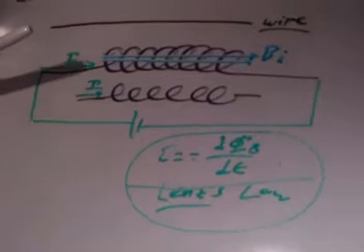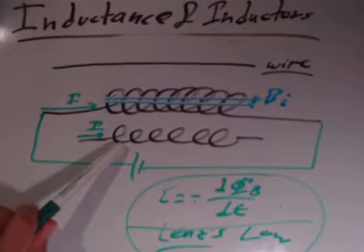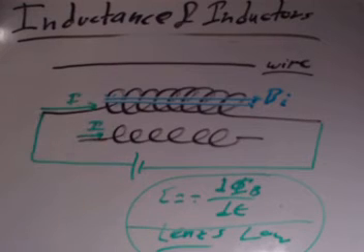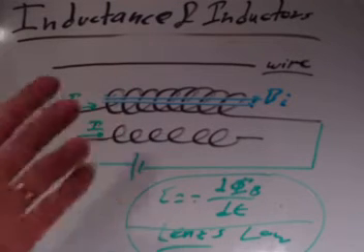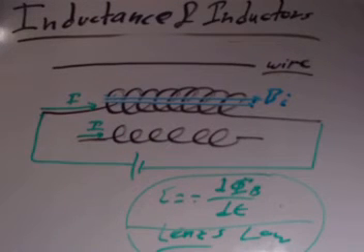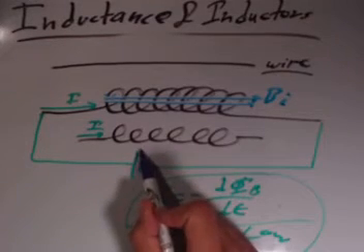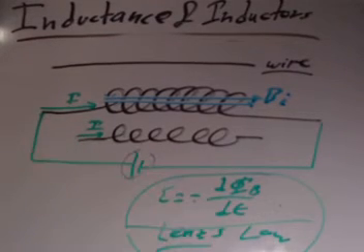So you go back to your good old inductor here and go, okay, you went from this inductor that had no magnetic field, you're trying to inject current into it, and you know that when current gets injected, a magnetic field is going to build up. But you want to oppose changes in magnetic field. That's what these two laws tell you here. So what this system is going to do, just this simple coil of wire, is it'll say, okay, you want to build up a magnetic field like that, and you'll likely eventually win, and usually you do win because the battery here is sort of like an infinite power supply. You just keep pumping the current in.